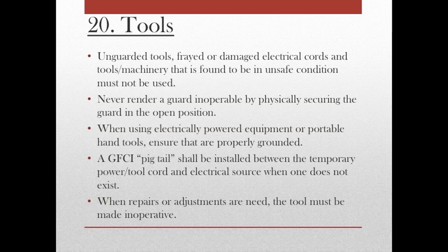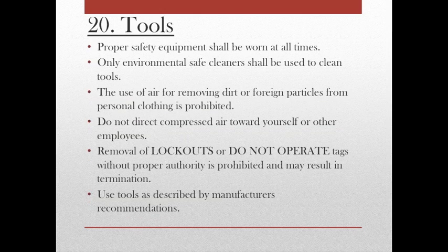When repairs or adjustments are needed, the tools must be made inoperative. Follow de-energized or lockout tag-out procedures. Safety guards may only be removed for such purposes and reinstalled prior to use. Proper safety equipment shall be worn at all times, for example, safety glasses, face shields, or ear protection, etc.